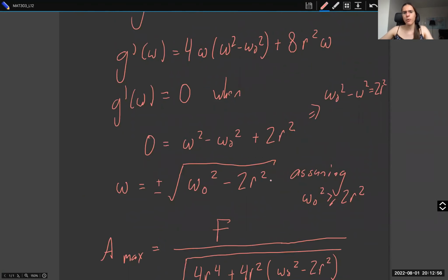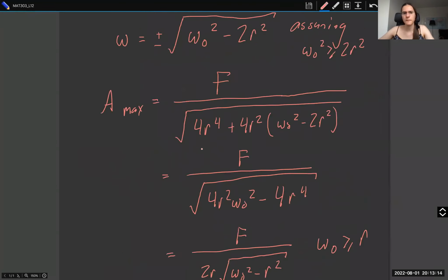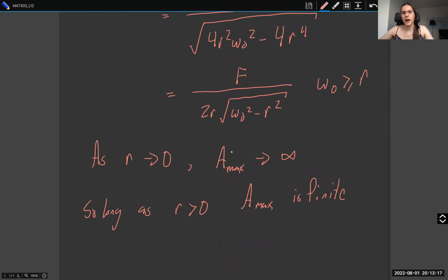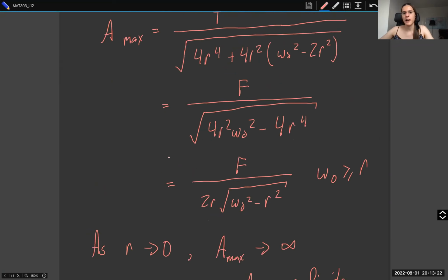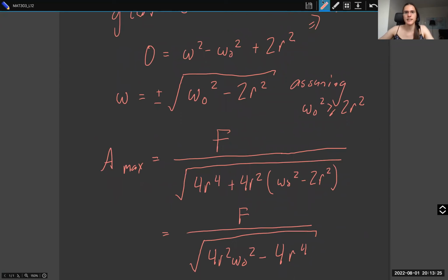So I think that both of these are going to be minima. It's a 4th-order polynomial, and so overall it's going to look like a quartic, but then it's going to look like this essentially. So there are going to be 2 minimum solutions at both of these values. That's what it's going to look like. But at either one, if we assume that omega is positive, then we can take the positive root without loss of generality. And so the resonant frequency is this. This is the new resonant frequency. Rather, this is the damped resonant frequency.